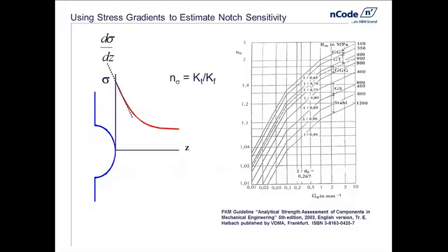On the left-hand side, you see kind of a schematic where we have a notch in a part, and at the bottom of the notch, we're obtaining the stress from the finite element results. We also have the ability to drill into the part and to calculate how quickly that stress drops off, or the stress gradient. That stress gradient is used to estimate the sharpness of the notch.